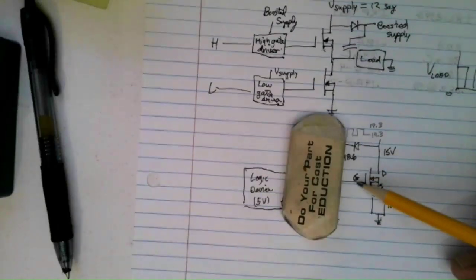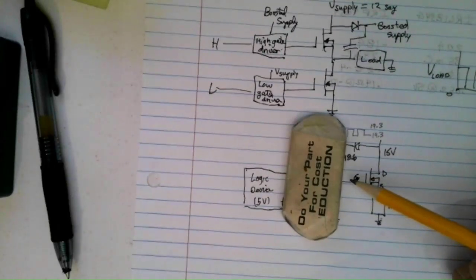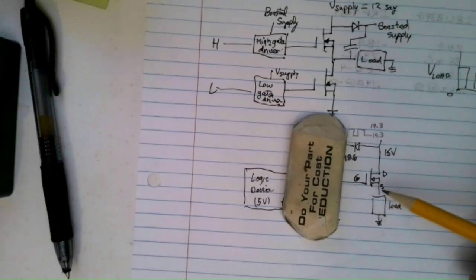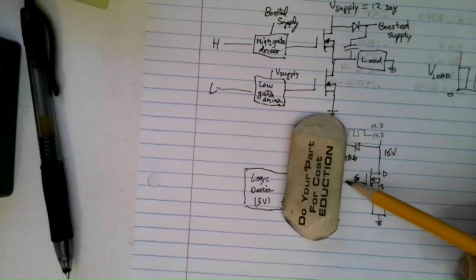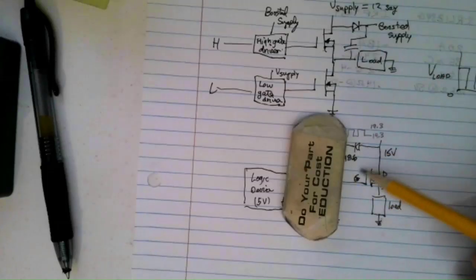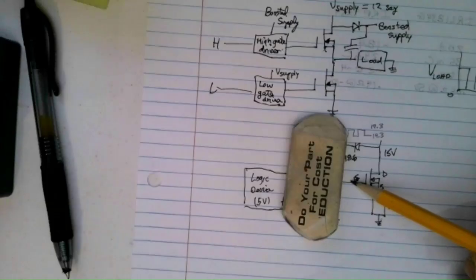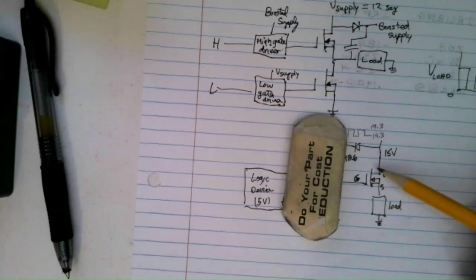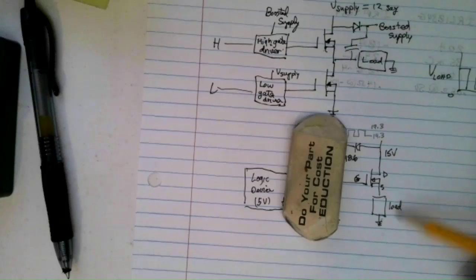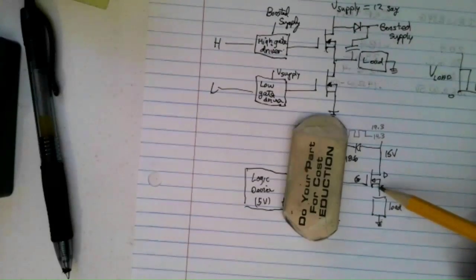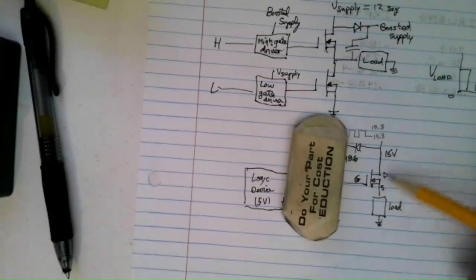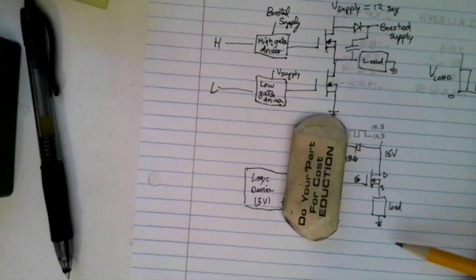And I think what we showed last time is for a 20 amp NFET part, which we'll look at again in just a minute, that if you pull the gate right up to the supply voltage, which is what you would want to do, the source, if you had a 15 amp load, would want to be about 3.5 volts less than the gate to get this part to turn on enough to give you your 15 amps.